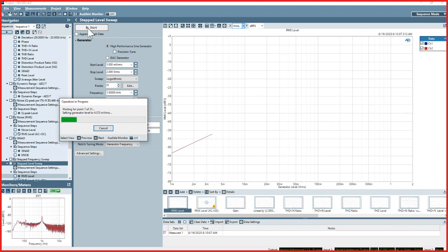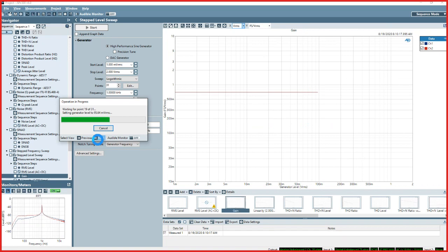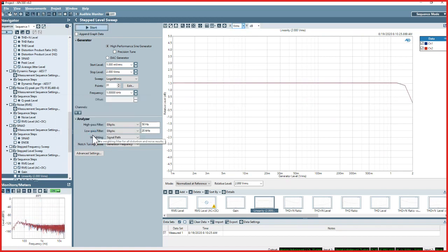The main thing we're looking for when we test any converter is this particular graph, which isn't so exciting. But here what we have is an amplitude linearity graph. And what we're looking for here is the range over which the gain function of this converter is flat or linear. And what you can see is just above 1 volt is where we get to the clipping point of the converter, and that's where it becomes nonlinear.